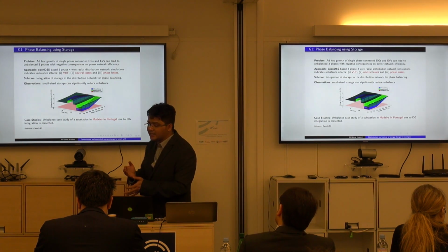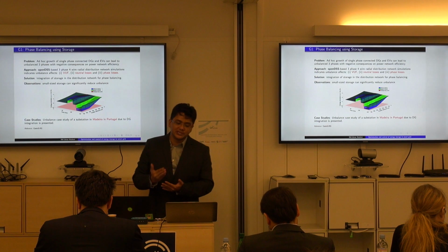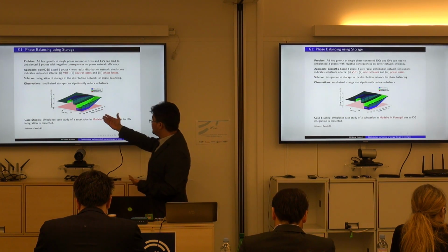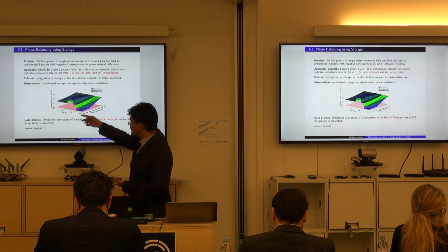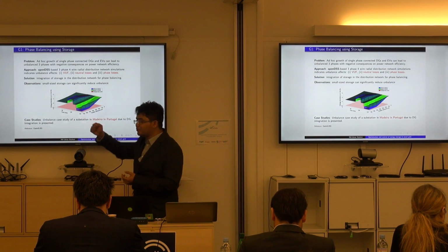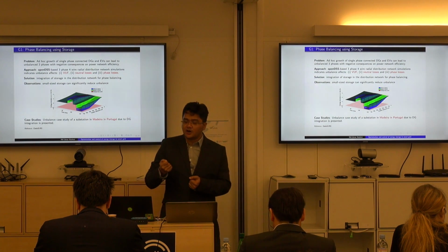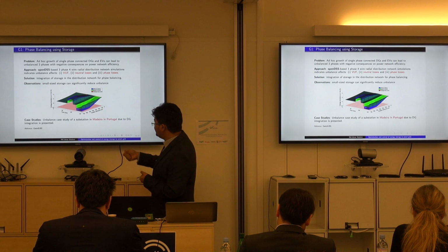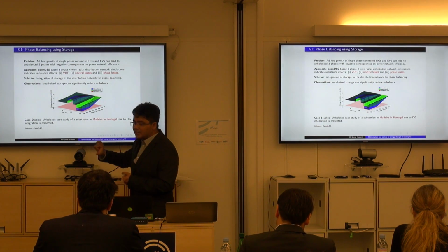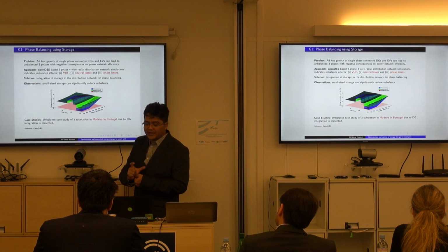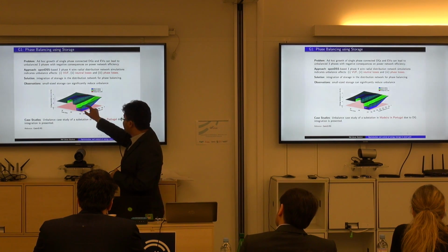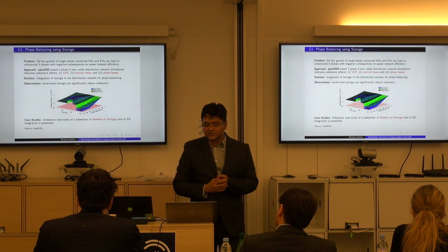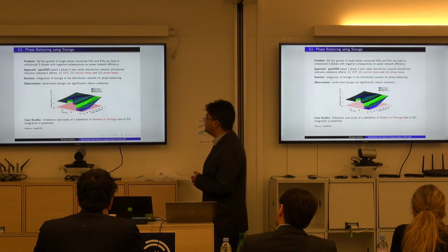If my imbalance is 10 megawatt and I'm using a 10 megawatt battery to solve it, it's a very bad solution. So in this case, there's an imbalance created, and we put a battery of 20% size at the end of the feeder of a radial distribution network, and we observe that with a battery ramping size of 20% of the imbalance magnitude, we can significantly reduce, in this case, the voltage deviation. Which means that batteries can facilitate balancing.